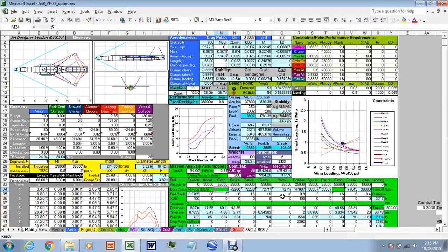And the reason they can do that is they're wearing full body anti-G garments which squeeze their body, and they're also pressure breathing 100% oxygen which squeezes their body from the inside. And so the physiological stresses from a rapid decompression are much reduced, and they feel like it's safe to fly above 50,000 feet in those particular aircraft.